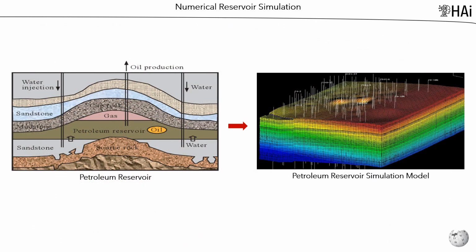Numerical reservoir simulation is an area of reservoir engineering, in which mathematical models are used to predict the flow of fluids, typically oil, water, and gas, through porous media. Traditional finite difference simulators dominate both theoretical and practical work in reservoir simulation. Conventional physical simulation is underpinned by three physical concepts: conservation of mass, isothermal fluid phase behavior, and the Darcy approximation of fluid flow through porous media. But it should be noted that finite element models are a higher precision alternative, and as expected, have higher computational cost.